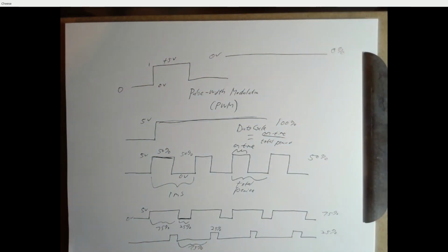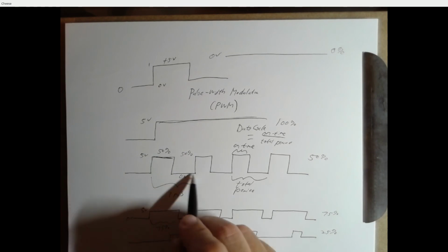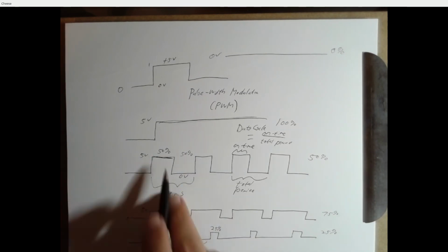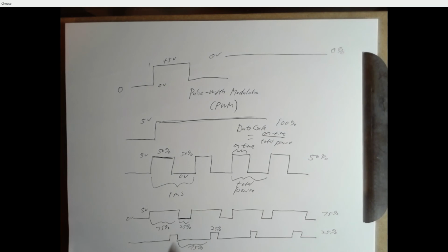And this is a general concept. We use this anytime that we want to use a digital device to control something that's more analog, like a motor that is able to run at something more than just full power or no power, has levels in between. We can use this with LEDs, right? LEDs are always either on or off. You put in enough voltage and they turn on and they're very bright. And if you go below that voltage, they turn off and they're completely dark. So how could you make an LED run at half intensity? You can use pulse width modulation. If you send 5 volts and then 0 volts and alternate back and forth 50-50, that LED will look like it's half as bright.